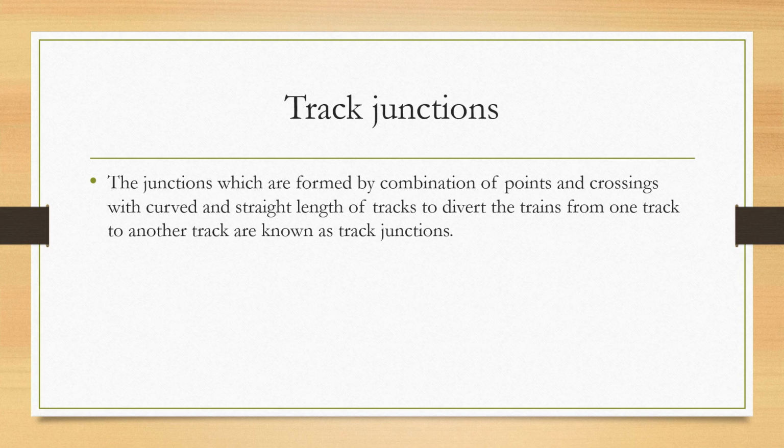Sleeper spacing and packing. These should be checked, with attention to the sleepers placed at the heel of switches. Packing of sleepers should be done for proper working of the turnout track.